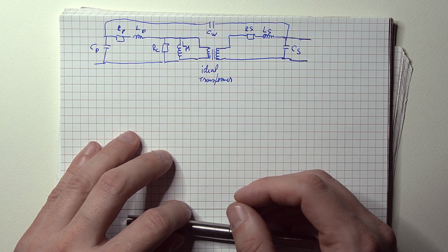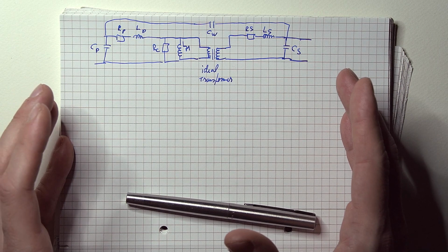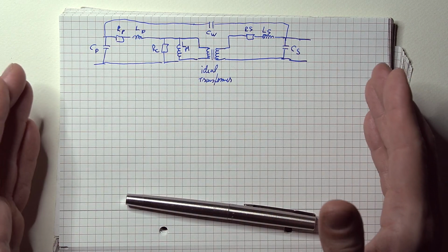The actual inductance value and the various parasitics of the transformer play a key part in the actual frequency response of the circuit. You can't simply have a transformer with any number of turns and just respect the turns ratio. You have some other things to also consider. Now, I don't want to go into too much detail on this, since I covered this in an older video, but the equivalent model of the real transformer looks something like this.